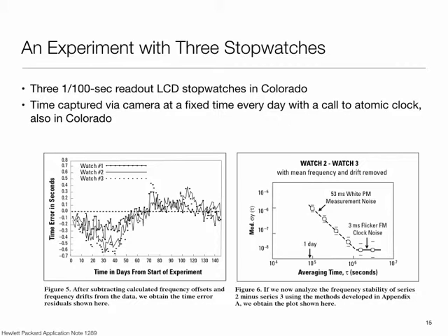So you cannot simply calculate things for way out into the future. Somehow you need to keep track on a shorter basis and revisit your decision about how many counts the counter should advance by before the interrupt. So it's not a decision that you can take at the time the application made a request.